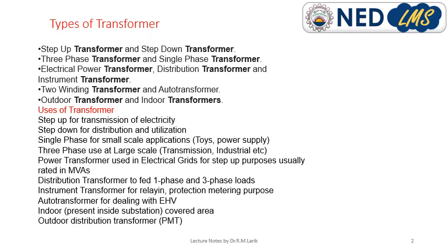So transformer types are step up, step down, three phase, single phase. We have power transformer, distribution transformer, instrument transformer, two winding, one winding transformer, indoor transformer, outdoor transformer. The uses, as I said earlier: step up for transmission purposes. When we want to transmit our electricity, we step up the voltage to a high value and transmit the electricity by using a step up transformer. Step down transformer for utilization